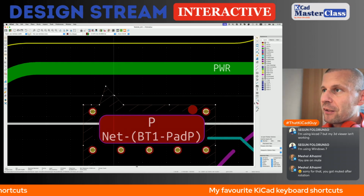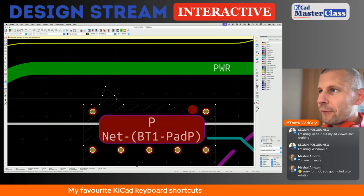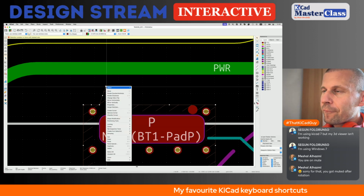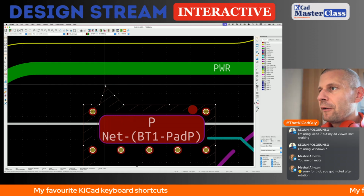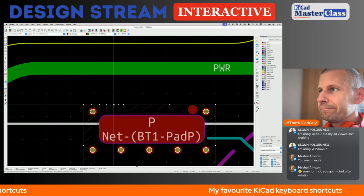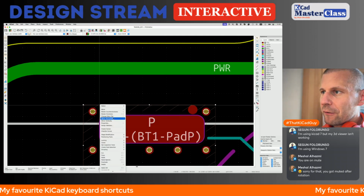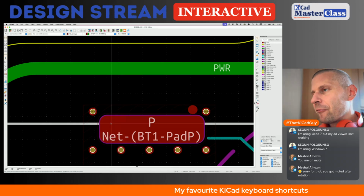It's very, very fast. You can do it from the contextual menu, like you can see here, create corner, or here when the corner is active, remove corner. But it takes quite a lot of time by pressing the right mouse key and choosing from the menu. So F1 and shift F1.